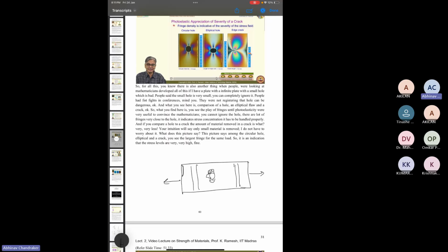And this assumption is very useful because in most engineering applications, you have some particular places where you are applying your load, for example, like this, and you will always have some stress concentration there, because even if you, for example, have trusses, you have some rivets which are used to join the trusses, and these are the points of loading. So here you will have the maximum stress being experienced. But from a design point of view, you will just assume that uniform stress is being experienced by the cross section all over. And you can make this assumption because as you move away from your point of loading, it actually becomes uniform. So in most cases, it is fine to make this kind of an assumption.